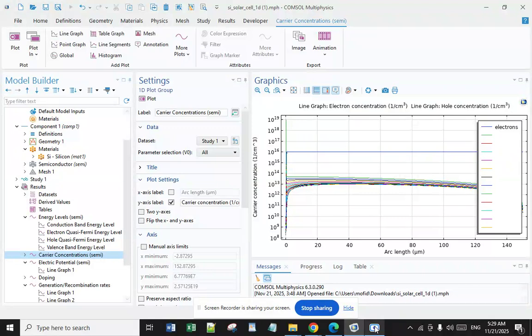In an ideal silicon crystal at 0 Kelvin, all valence electrons take part in forming covalent bonds between silicon atoms, and therefore there are no free electrons in the lattice. This situation is schematically shown here. At temperatures higher than 0 Kelvin, the bonds start to break due to absorbing thermal energy, and this process results in the creation of mobile electrons and holes.